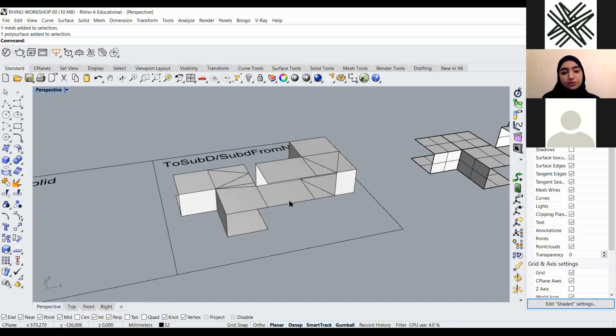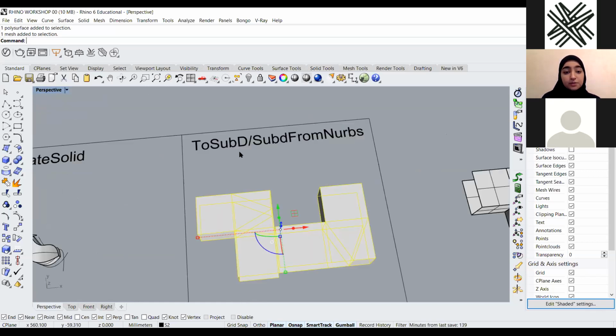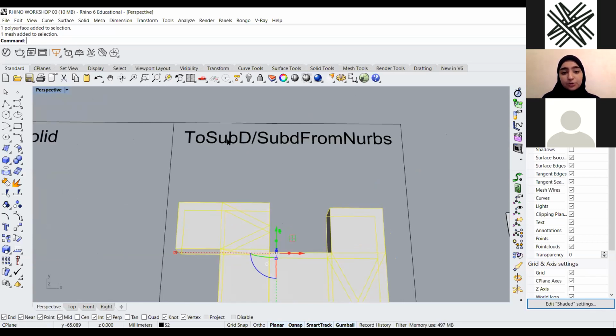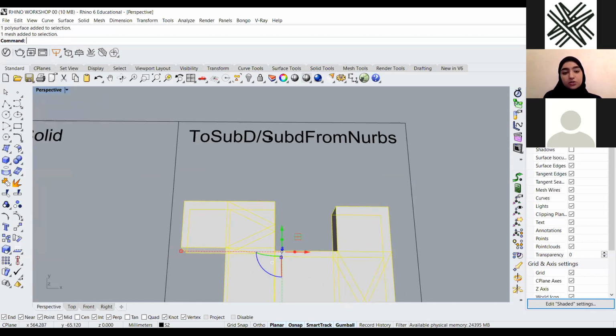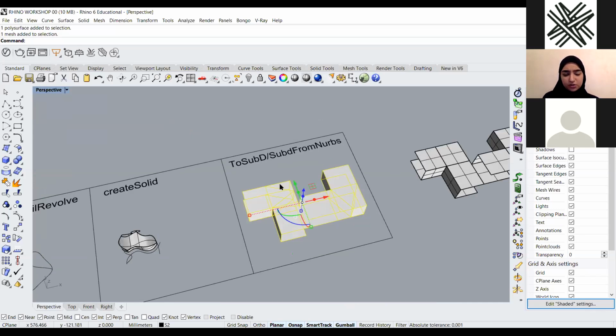Then what we have to do is to use the command. It's either ToSubD or SubDFromNURBS. And these two commands are called hidden commands. So it doesn't show until you type the whole word and click enter, then it's gonna show. Even if you just type ToSub, it doesn't show. You have to write the whole thing. So it's either this for some versions and this one for other versions. So try both and see which one works.